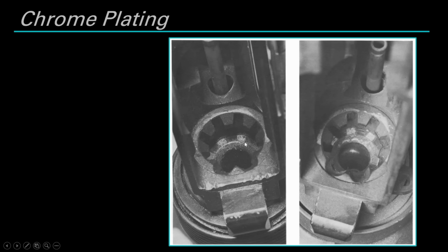Once a fired case gets stuck in the chamber, typically the bolt carrier's extractor won't be able to get it out on its own, and you'll have to take a ramrod from the muzzle of the gun and beat the case out of the chamber. For some particularly tightly sealed cases, this can take as much as a minute to clear, and limiting yourself to one round fired every minute before the next case seals itself in place is like muzzleloader territory, and it's really not a good situation to be in.